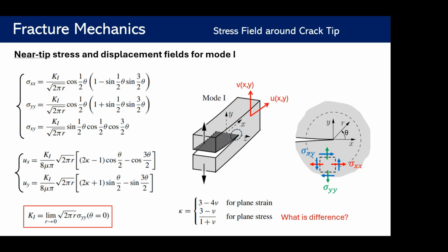If you assume its plane is the XY plane, in the Z direction, normal to the XY plane, the thickness of the plate is very small. So for thin problems, you can assume the problem is in plane stress condition, like this paper. And usually we assume that the stress in the direction normal to the plane is 0. That's what's called plane stress.